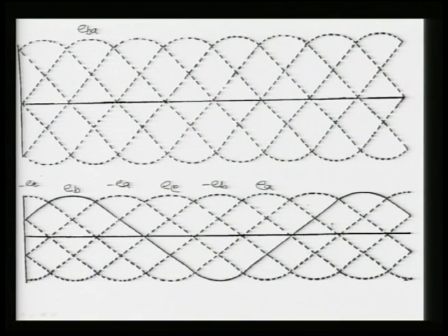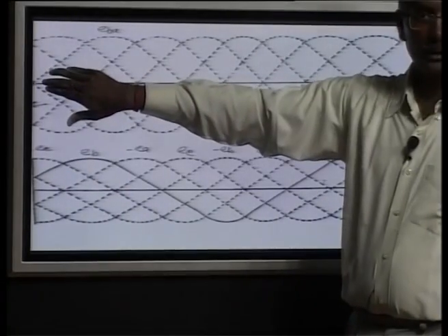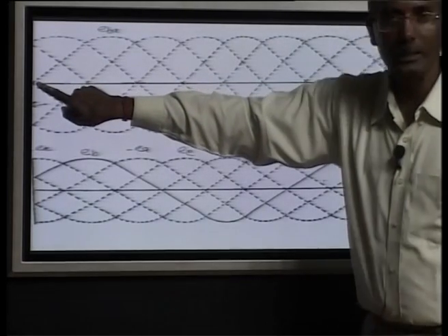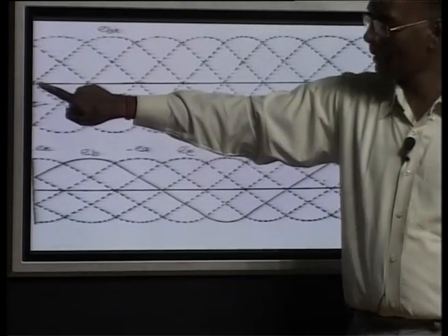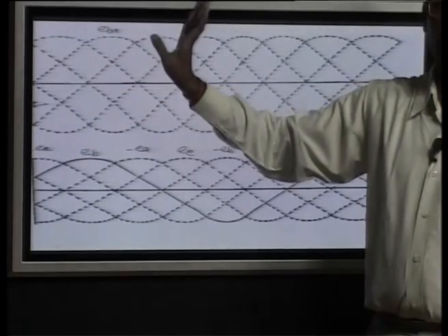Now you can see in this topmost figure that we can start alpha from here at any time, because of the voltage across valve 3 in the star-star connection 6-pulse converter, we can fire and then it will conduct. If you delay by some angle alpha, it hardly matters, the voltage will follow and it will conduct.